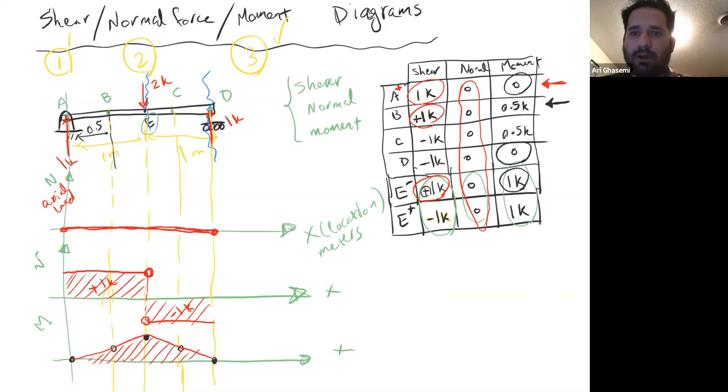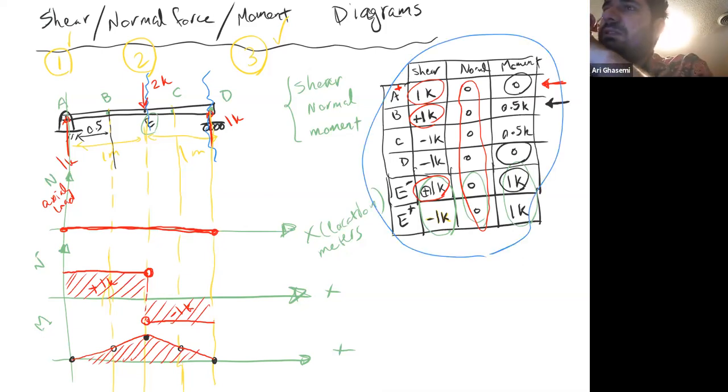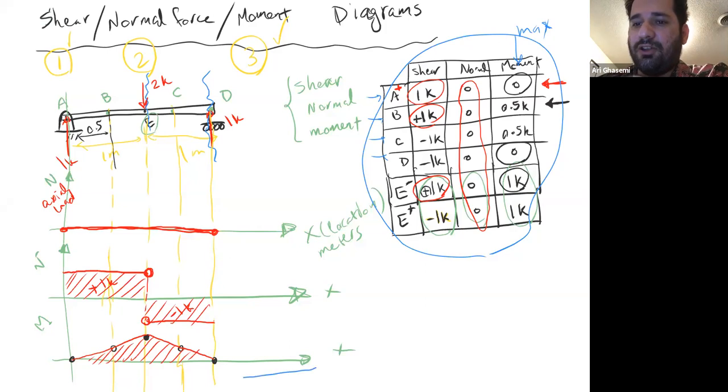So right now, if I ask you where my maximum moment happens, what is the answer? Well, if you have this little table, and let's say the table is obtained for 200 points across this beam, then you have to go through all these 200 rows to get the maximum moment, right? And that procedure is very time consuming. You don't want to do that. But what's the advantage of plots? The advantage of the plot here is that I can say the maximum happens exactly in the middle.